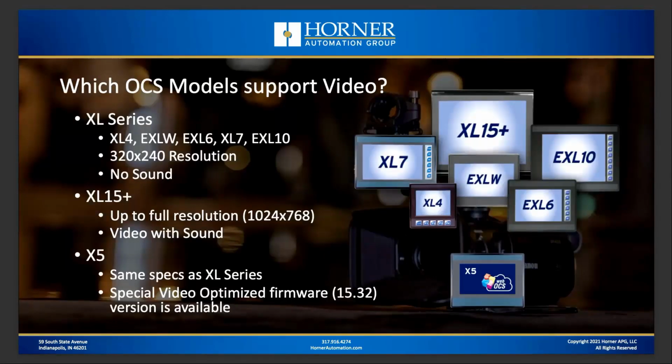Okay, which OCS models support video? Well, a lot of them do, actually. The XL series from the XL4 on up, that includes the 6-inch widescreen, the standard 6-inch, the XL7, as well as the EXL10. All those models support video playback. Now keep in mind, we're not talking about full cinema viewing here. We're talking about 320 by 240 resolution. The idea is to get the information to your customers while the OCS will still spend a bulk of its time controlling the machine.